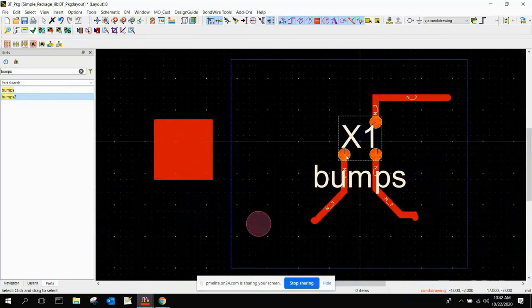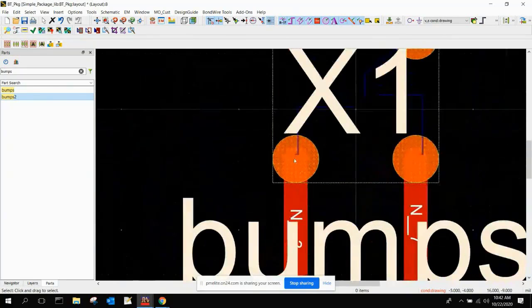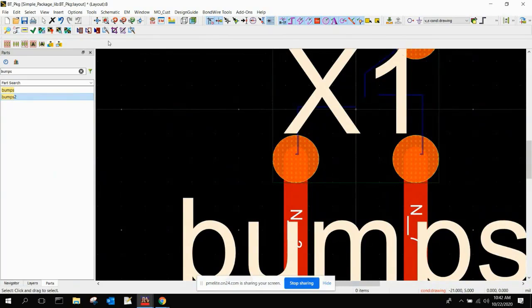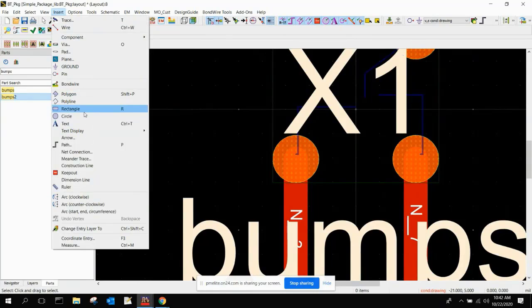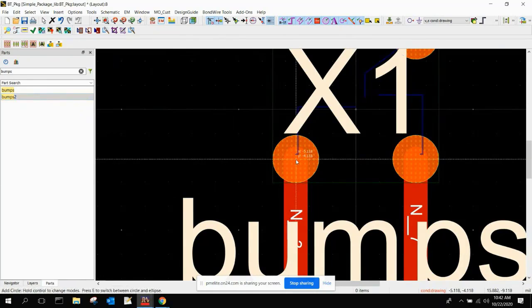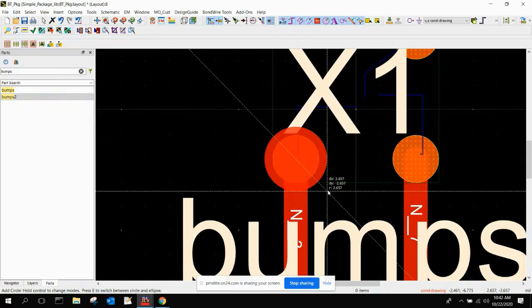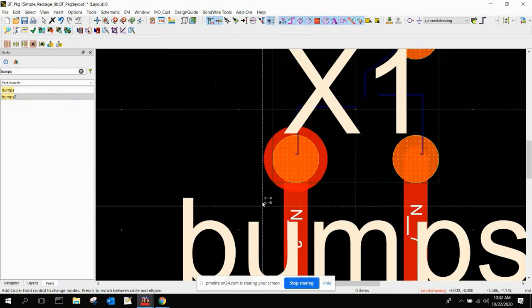If you're doing a package design, one example: we've got a pad now, and it's the same landing as the solder ball. But when the solder ball goes on a package, in a lot of cases, I'd actually want it to be bigger. Because usually if the landing is exactly the same size as a solder ball, you're going to have placement errors, problems like that. This is probably more like what I'd want to have, a larger metal to land on.